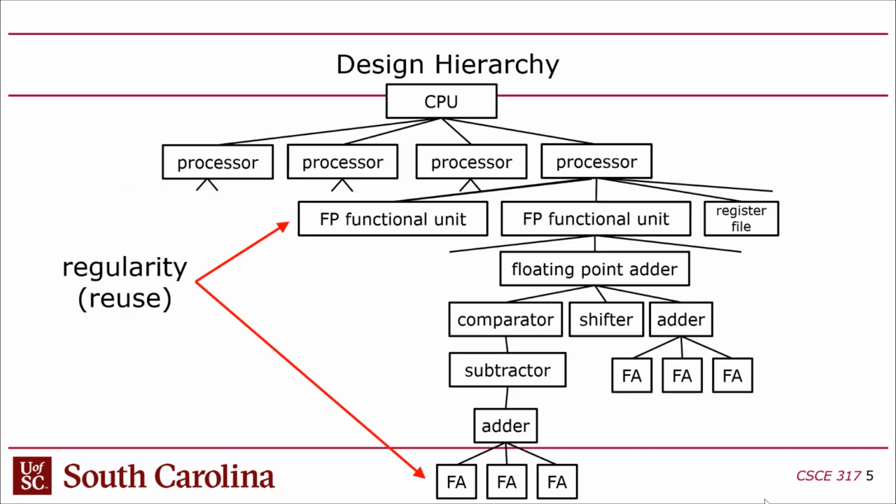And then there's this notion of regularity too, which is where you're trying to design your modules for maximal reuse. It's the same concept as writing a method in any programming language, right? You want to maximize the reusability of your modules. You might say, well, that's obvious, but sometimes it's not. When you're writing the code, you may not know how to divide your design up into modules. It's not always obvious. You could write a really long module and have a whole CPU in one module, or you can write a whole bunch of small modules that collectively comprise the CPU.